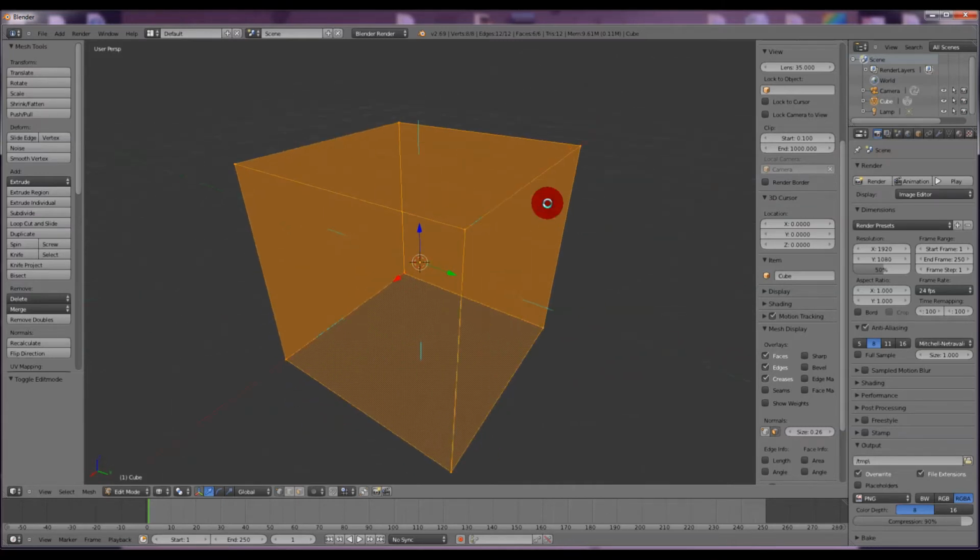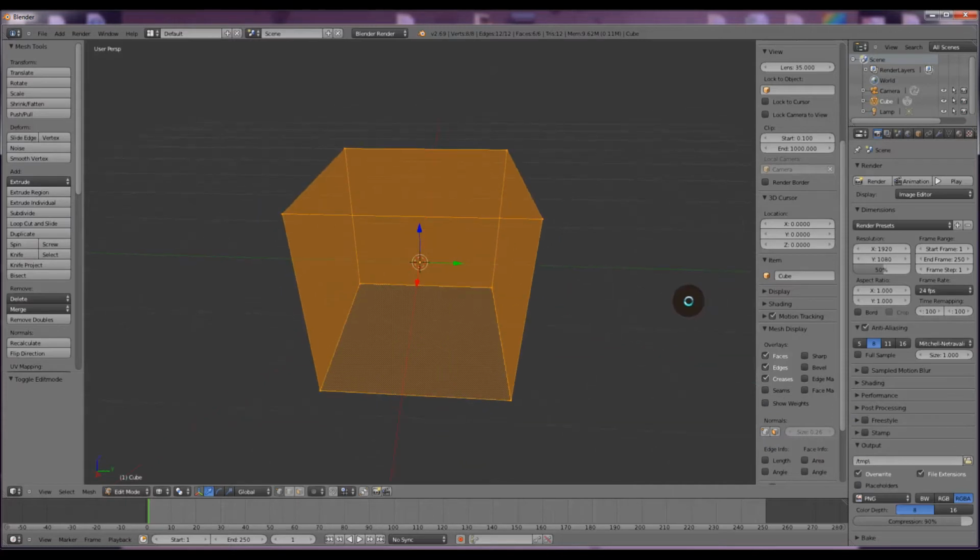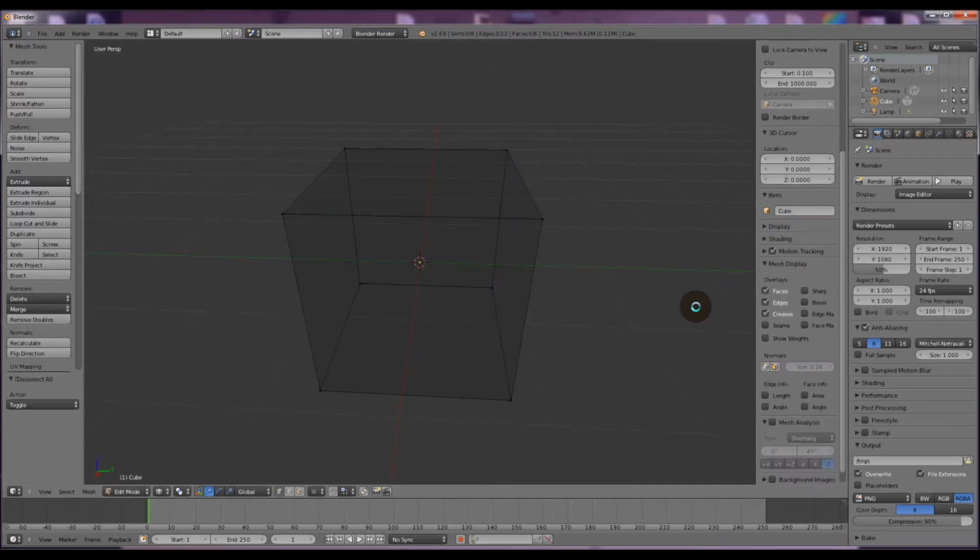When you add a primitive, they're usually on the outside of the surface. But as you can imagine, if you wanted to make a room, you would want your normals pointing inwards so you can see the walls. But I digress. Okay, we're going to work on a cube to try and keep things a bit simple for the time being. Let's put it into solid mode again.